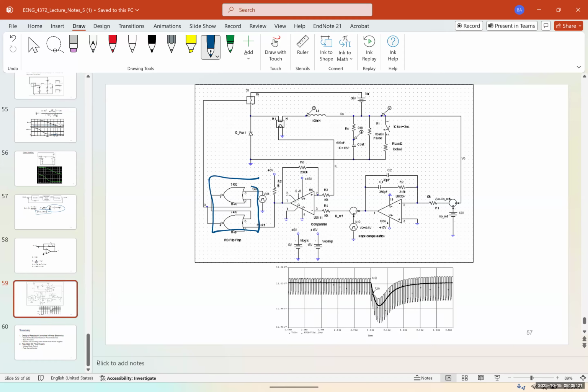And this actually gives us the flip-flop and latch. A flip-flop is actually a latch with a clock. And if you have had digital design with me, you already know this. If you haven't, this semester in digital design you're going to learn about flip-flops and also latches, which are two NOR gates or NAND gates with feedback, where one of them gives feedback to the other one.